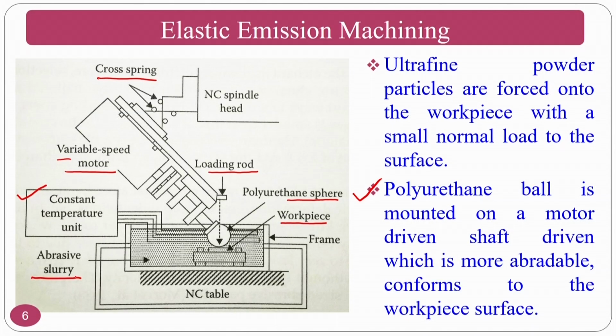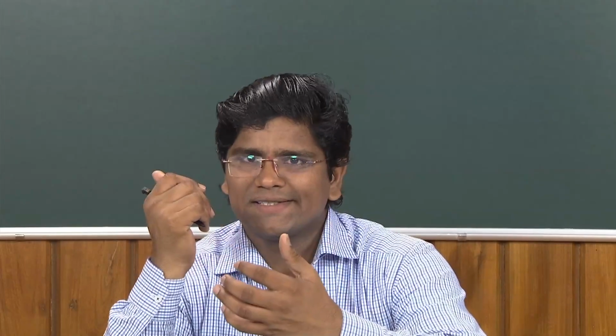Abrasive slurry says that it has abrasive particles as well as a carrier medium. Okay. So, in a lapping process also you will always have a carrier medium, which is water or oil or any type of thing along with abrasive particles. Okay. At the same time, some of the people call it a vehicle also. Okay. Some of the textbooks use the term vehicle because it is carrying the abrasive particles. Okay. Do not confuse carrier fluid, vehicle and other terms, some people also say slurry.